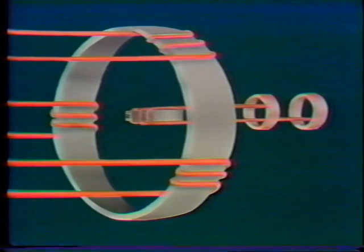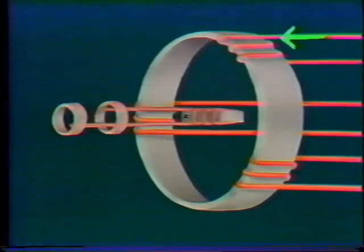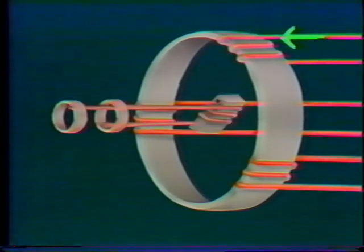As the rotor on the generator turns, a voltage is induced in the stator windings. Every time the rotor on the generator passes the A winding, voltage is induced in that winding. The voltage in the A winding on the generator causes current to flow to the A winding on the motor. Current flowing through the A winding on the motor builds up a magnetic field around that winding. The rotor on the motor aligns itself with the A winding because of the magnetic attraction.